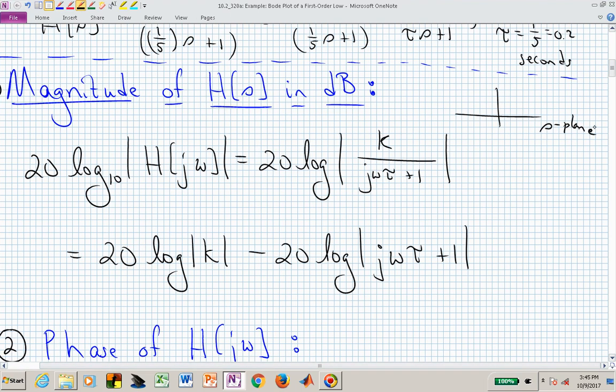Now here is our s-plane, and we are actually evaluating along this j omega axis for our transfer function. In our case, we might have a pole here. We are now looking at what the magnitude or the distance is between this point and that point, between this point and another frequency, and we're also looking at these angles as those change as we march up the imaginary axis, and we've talked about this in our frequency response behavior, or evaluating H of j omega graphically.